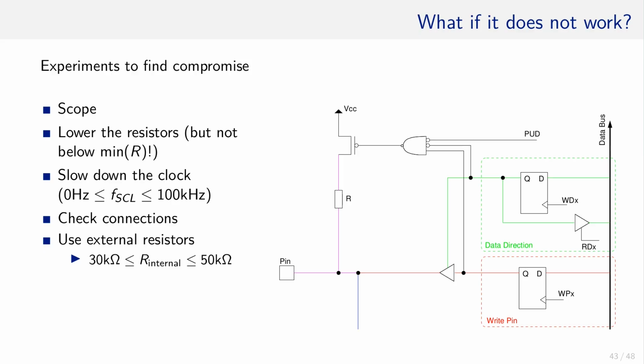One thing that I'm reading on the internet often is the usage of the internal pull-ups. Remember from chapter 4? I showed this diagram briefly mentioning PUD. If PUD and the DDR are set to 0 while a 1 is written to the pin, this transistor connects VCC through this resistor to the pin.